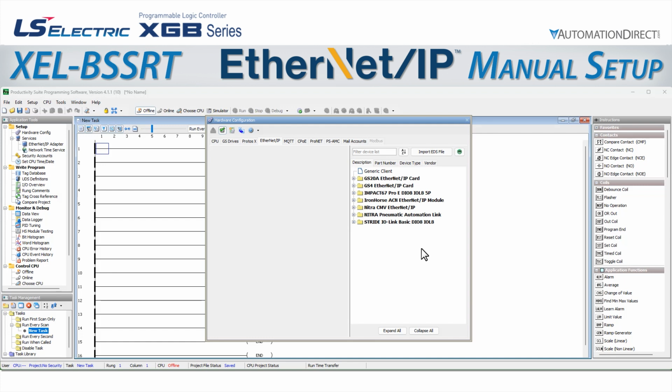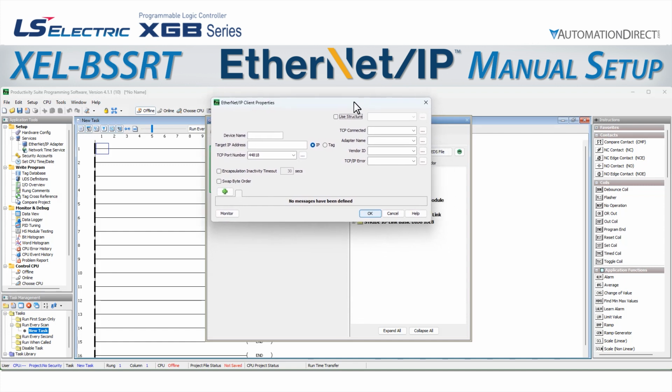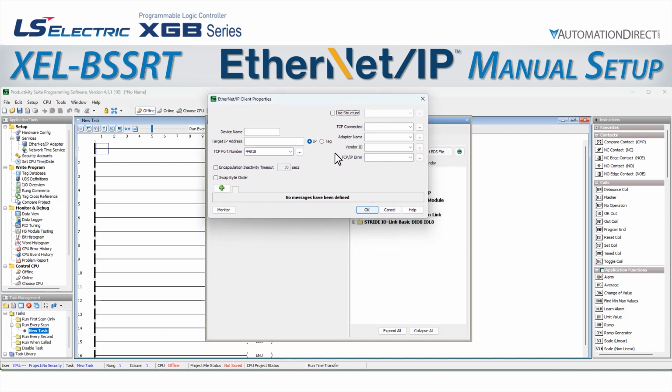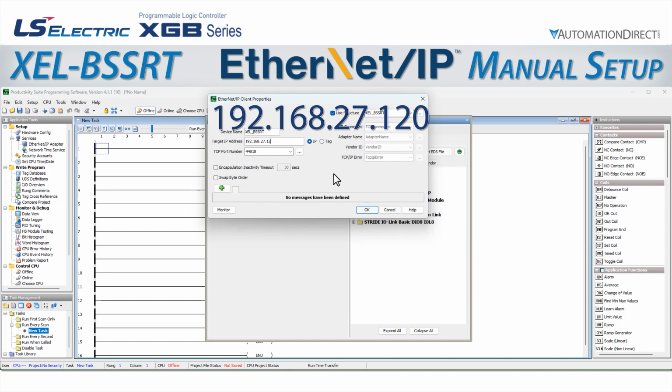There are some pre-installed options, but since we are setting up a manual connection without an EDS file, we will drag and drop Generic Client into the window. This will cause the software to open the Ethernet IP Client Properties pop-up window. We will use a structure and call it XEL-BSSRT. Our device name will be XEL-BSSRT as well, and our IP address is 192.168.27.120, since this is the IP address that we set for the BSSRT in our video on configuration.